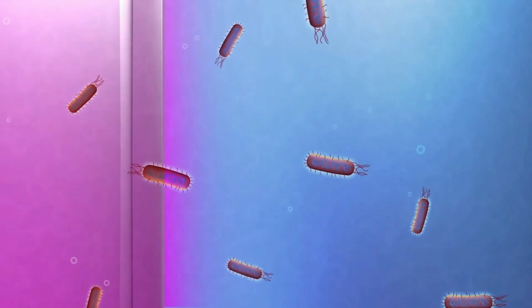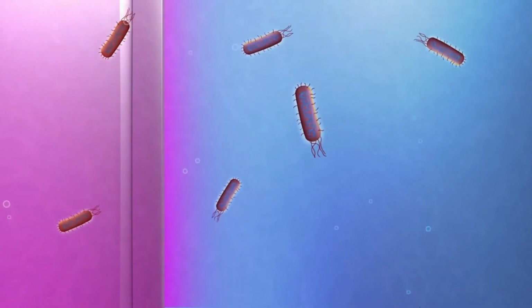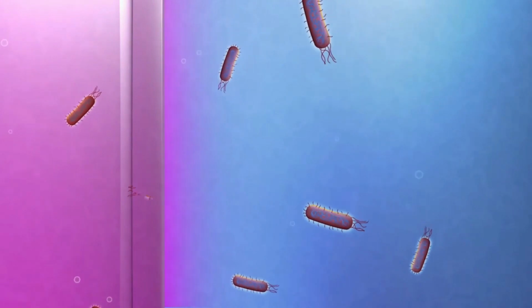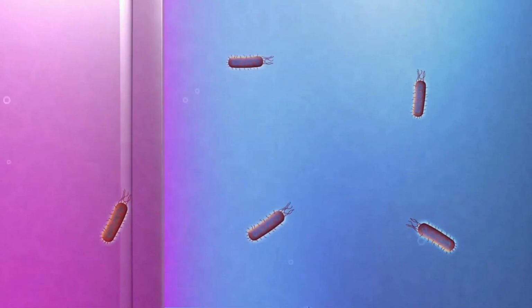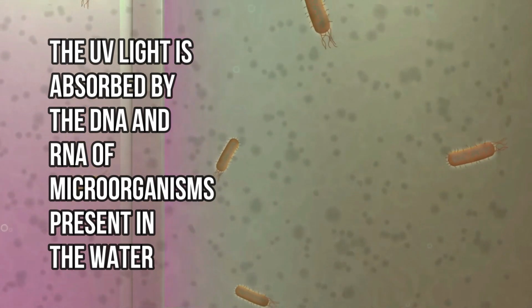This section delves into how UV light purifies water, its effectiveness against various pathogens, and how it compares to other water treatment methods. How UV light purifies water. UV water purification involves exposing water to ultraviolet light at a specific wavelength, typically around 254 nanometers. At this wavelength, the UV light is absorbed by the DNA and RNA of microorganisms present in the water.